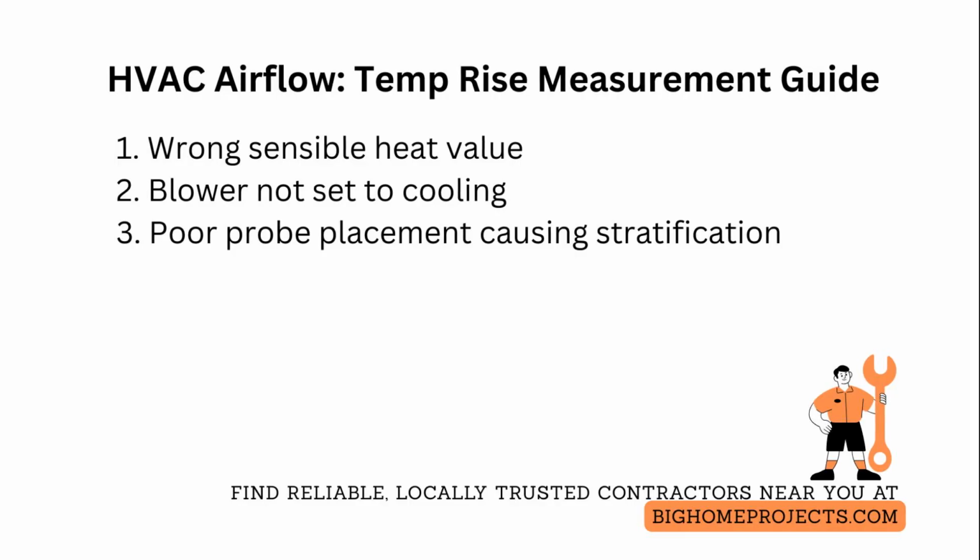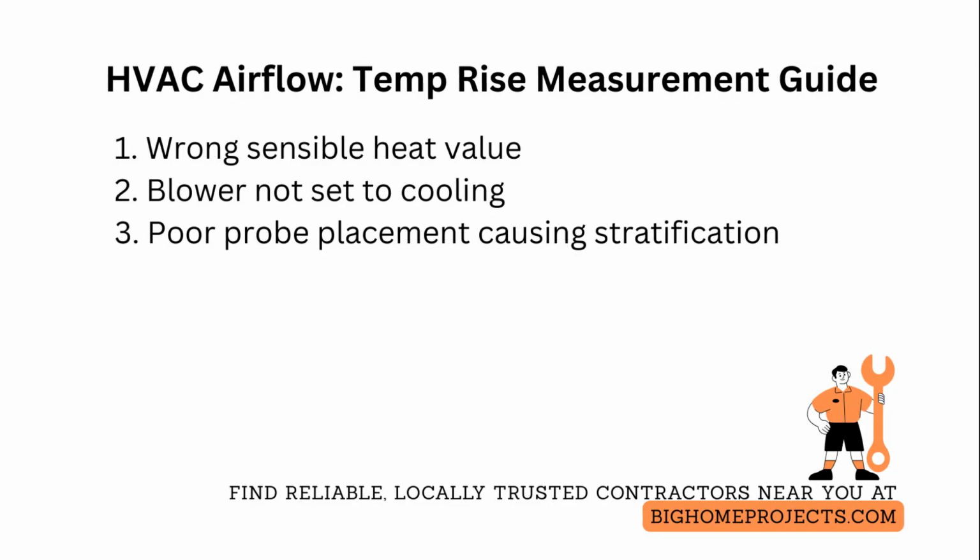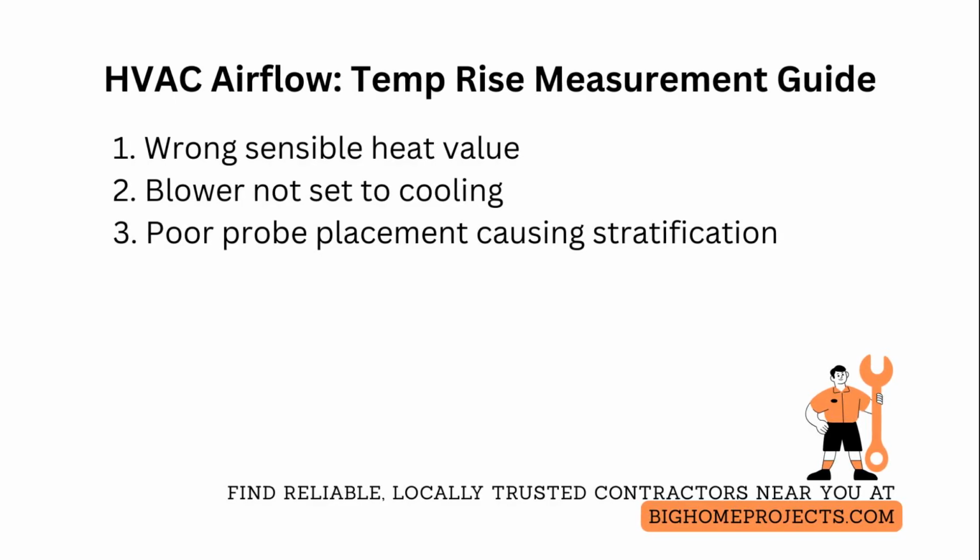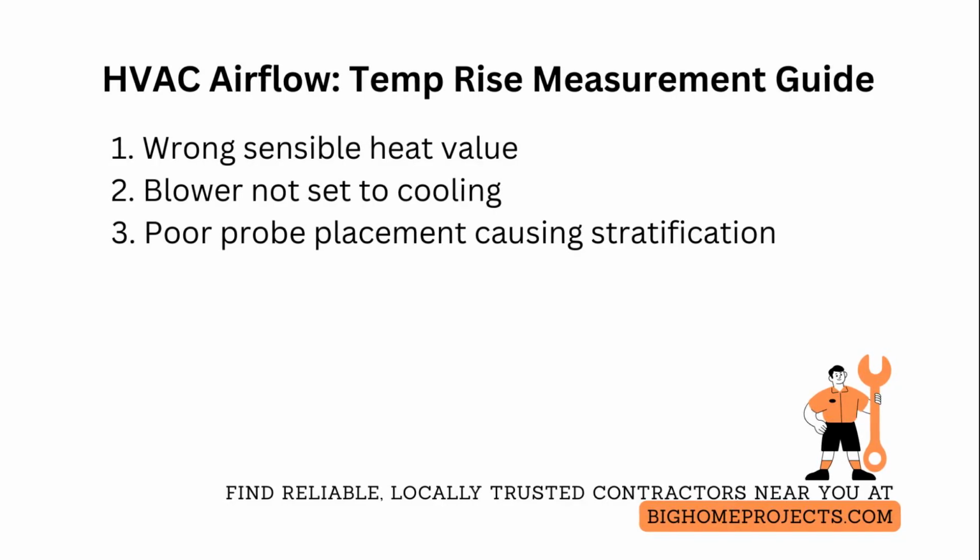One of the frequent errors is failing to set the blower to the correct cooling speed before measuring airflow for cooling mode performance. Fix this by switching the blower to the manufacturer's recommended cooling tap or variable speed setting, then rechecking supply and return temperatures.